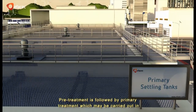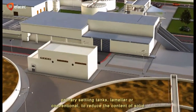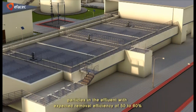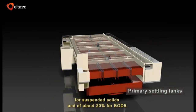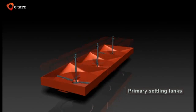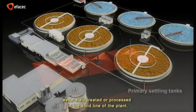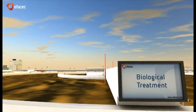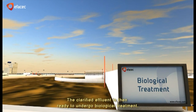Pre-treatment is followed by primary treatment, which may be carried out in primary settling tanks, lamellar or conventional, to reduce the content of solid particles in the effluent, with expected removal efficiency of 50 to 60% for suspended solids and of about 20% for BOD5. The sludge produced in the form of primary sludge will be separately treated or processed in the solid line of the plant. The clarified effluent is then ready to undergo biological treatment.